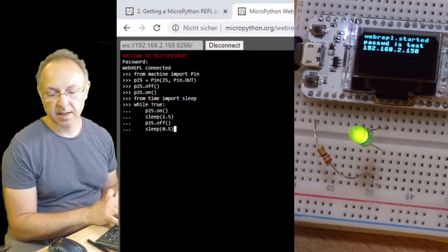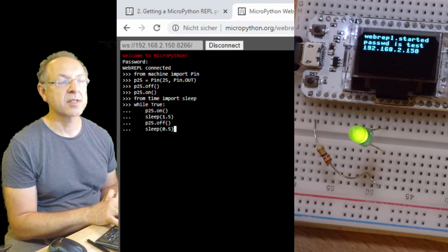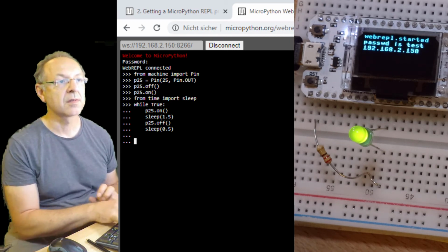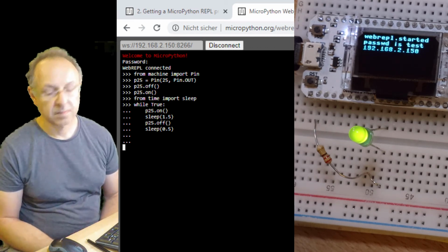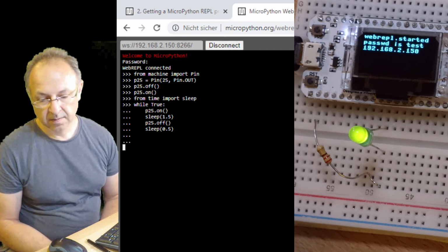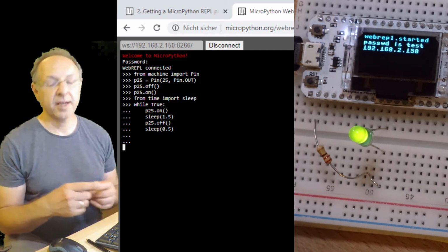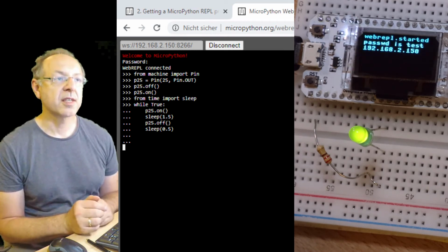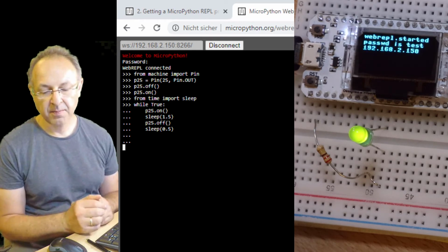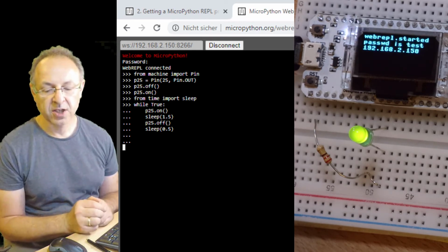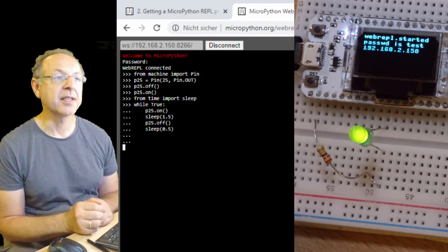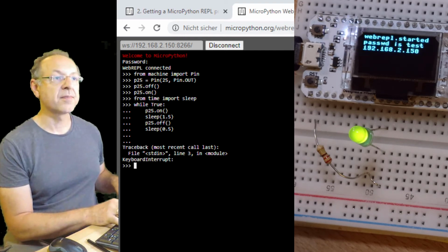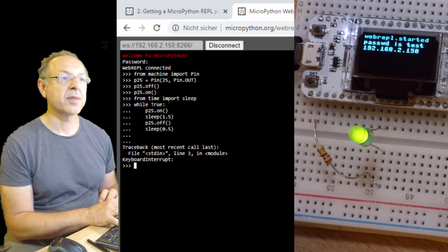and that's already it. So let's see, if we run this, we should see that the LED is on and off, but longer on than off. And the nice thing is we can interactively develop this. So we have now an LED blinking. Now what is interesting, we can use the same thing, but be much faster and can start changing how bright the LED is. This is called pulse width. So I stop this here. So I have interrupted it from the keyboard.